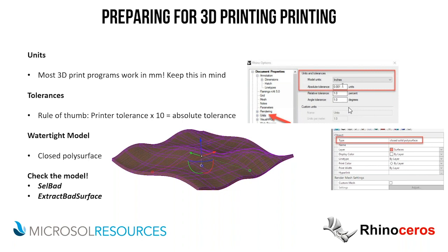Obviously, this is going to be different depending on the printer, depending on what you're printing. For example, this roof, let's say, you might think that it would be best to print it just totally flat on the printer. And you wouldn't necessarily be wrong, but what is going to happen is if you're using a traditional FDM or MakerBot style 3D printer, you're going to get a lot of support on the bottom, supporting these different curves and ridges.